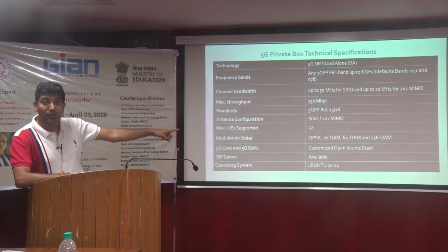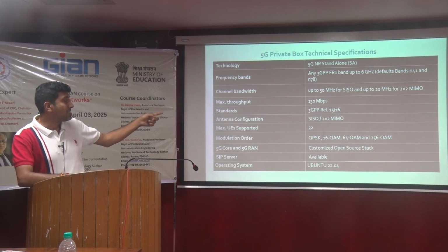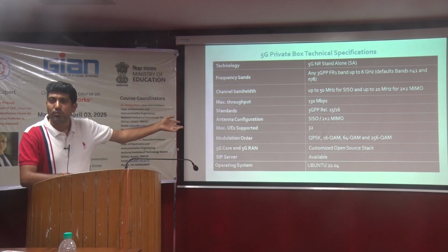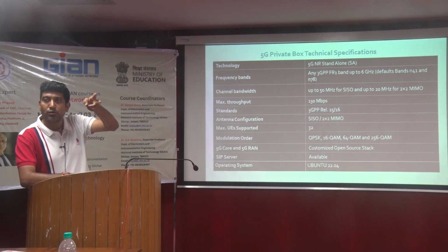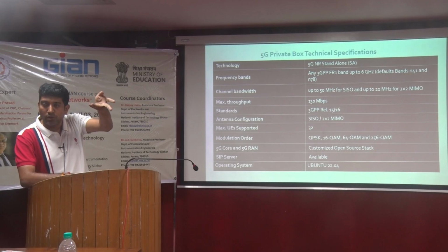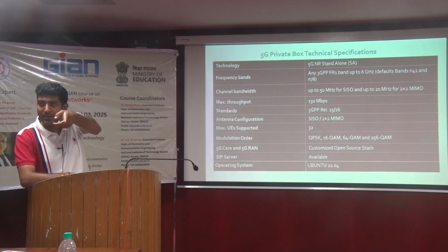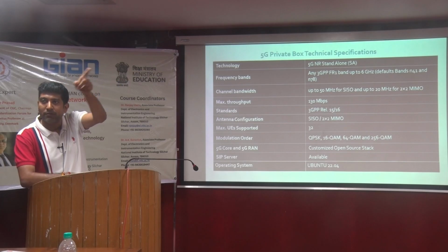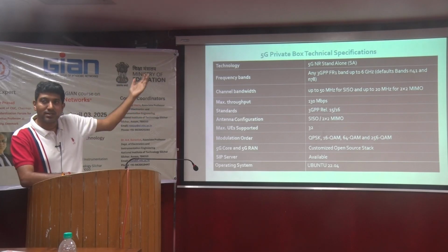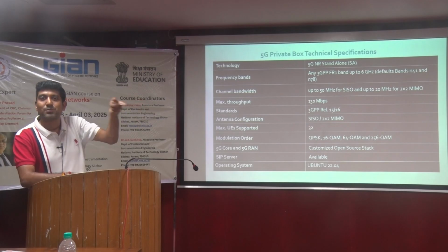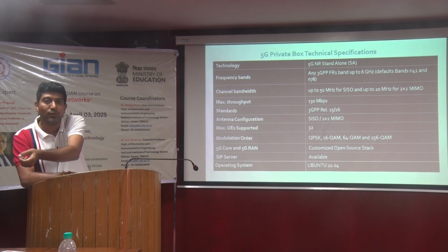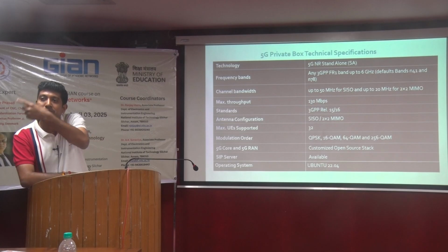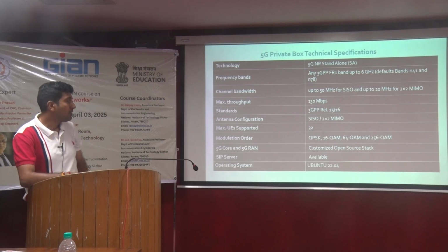The modulation which we can use, you can change the modulation schemes. QPSK, QAM. I presume most of you know what QPSK is, because it's quadrature phase shift keying. So you are using 2 bits to encode one symbol. So 2 bits, one for every phase. Say for example, you have a 360-degree phase shift. Every symbol corresponds to, say for example, the first symbol corresponds to 45 degrees, the second symbol will correspond to 135. So you are adding 90 for every such shift. So you have 4 symbols, total is 360, each having a separation of 90 between each other.